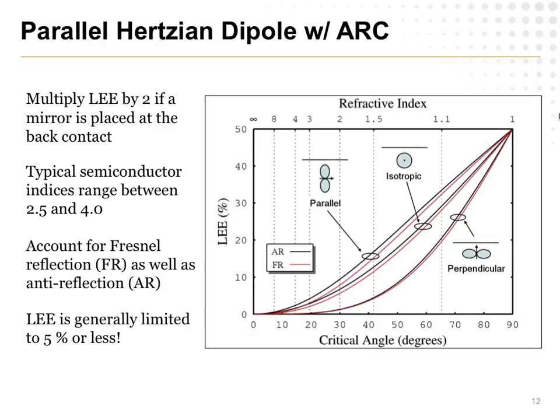That makes sense. In other words, you see your light extraction efficiency approaches 50% in the event that your index of refraction goes to 1. That's because all the photons that went up are just going to get out without any reflection, but all the ones that went down are being reabsorbed. So we're assuming that there's no mirror in your back contact.